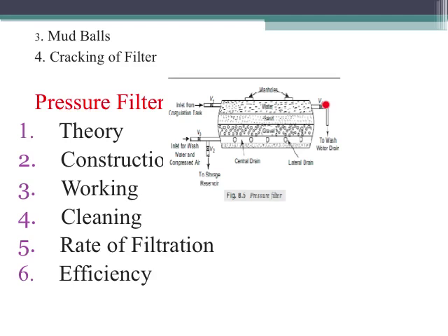The wash water and compressed air are sent through the base materials in an upward direction. The compressed air agitates the sand grains and the wash water washes the impurities adhered to the sand grains. The dirty water is exhausted through the wash water drain.